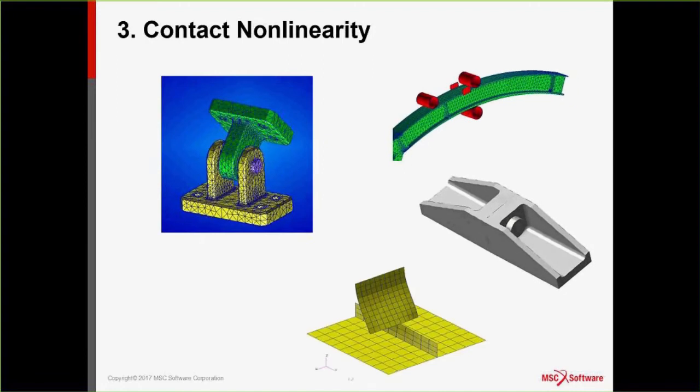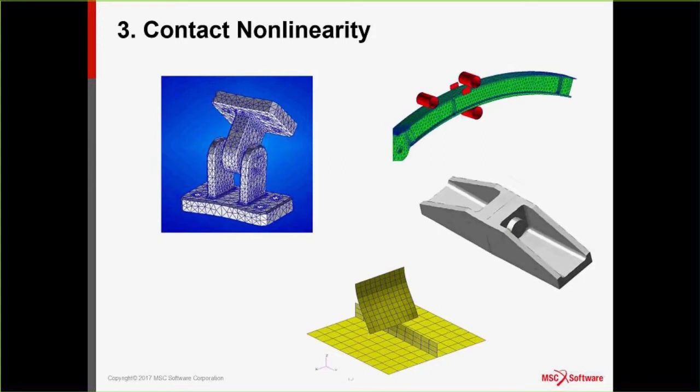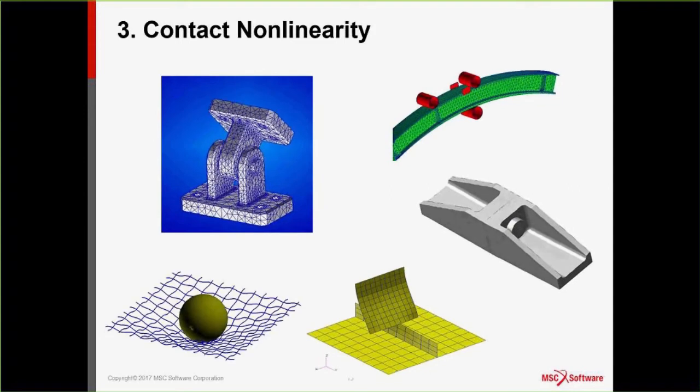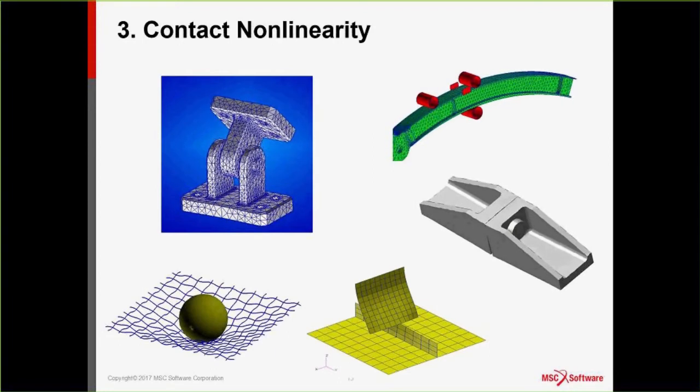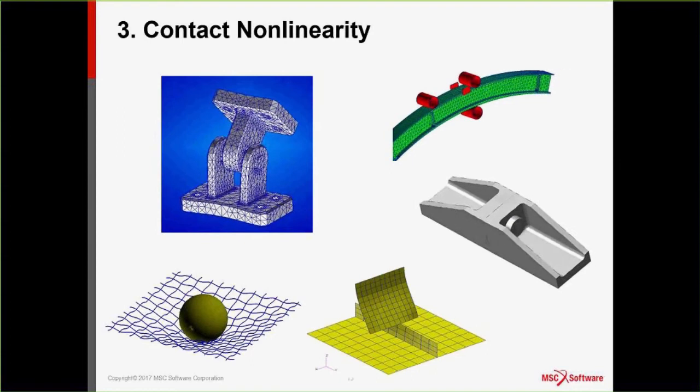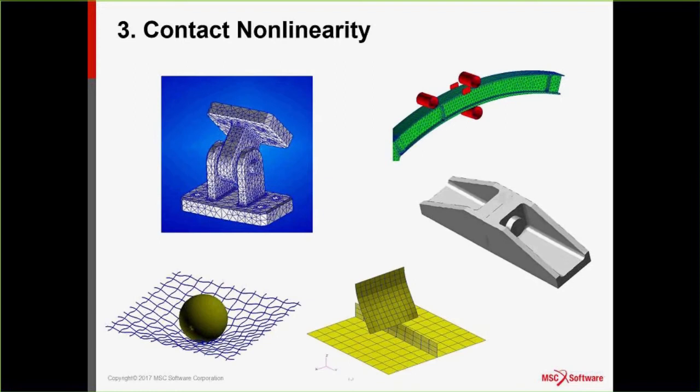You can certainly simulate contact between shell elements, shell bodies, face-to-face, edge-to-edge, and so on. And we get people asking us, one example, someone wants to simulate a cargo net capturing a UAV returning home. We can certainly do that. So this is a simple example showing you the beam elements are used to simulate the net, and it's capturing an object with the beams contacting each other and the beam contacting the solid.